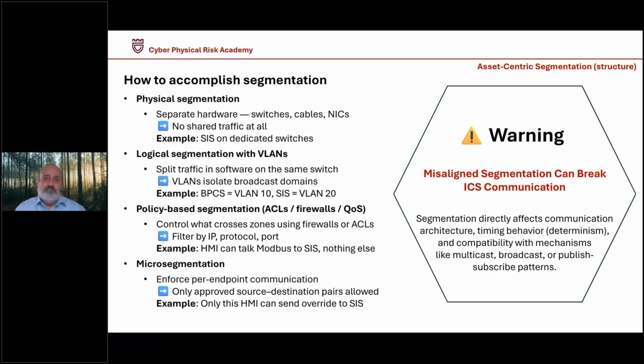In a process control system, there's a lot of different communications. I already mentioned Ethernet broadcast domain. There's broadcast traffic on Ethernet level. We also have multicast traffic very, very often for sending all kind of alarms and that type of information. And we have, of course, unicast from point-to-point type of communication. And all these traffic have their own demands on segmentation. If we talk about multicast, well, some protocols use level 2 type of multicast.